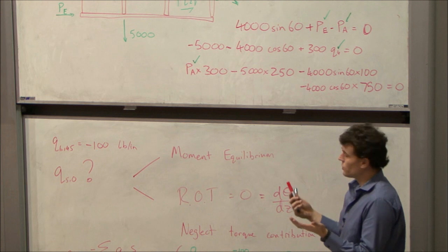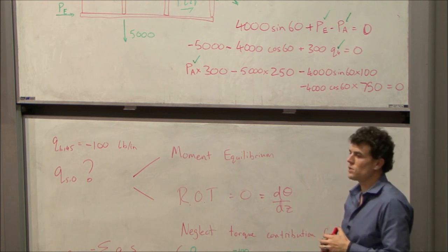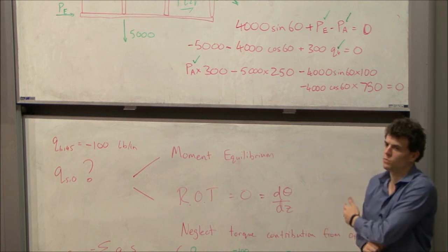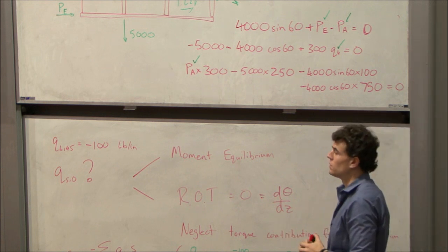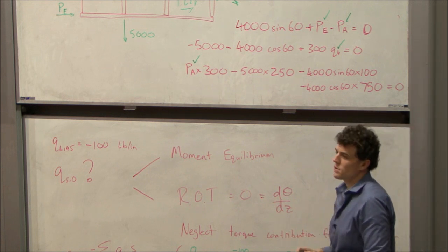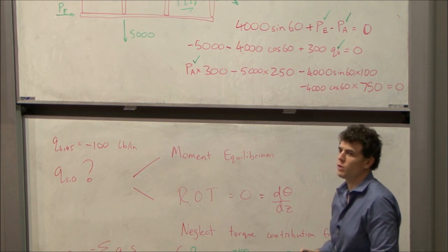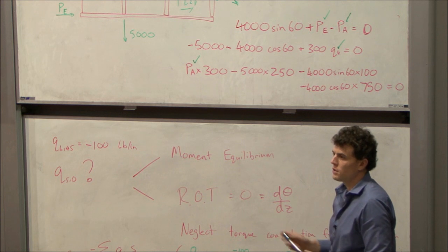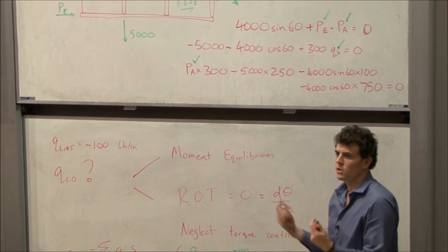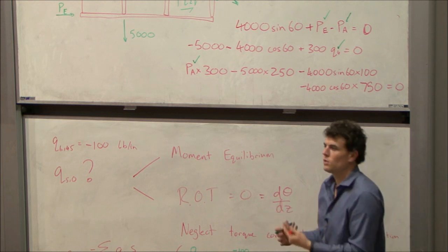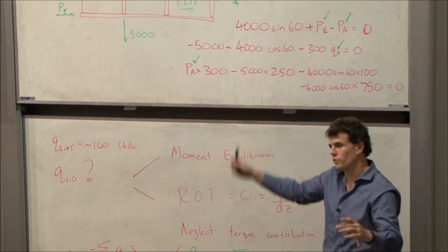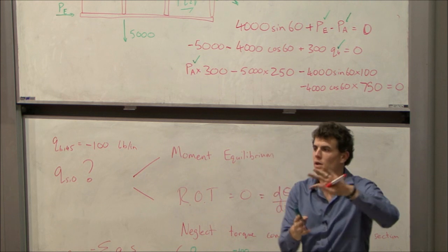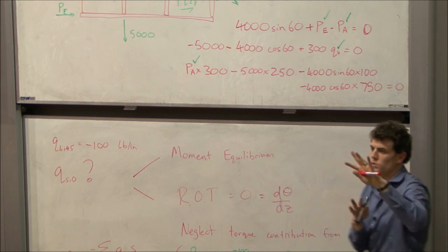So that's one way of doing this kind of problem. We can take slices anywhere we feel like and work out what the equilibrium on those slices is going to be. That's the equivalent of doing, say, a method of sections for a truss. You know your truss calculations: if you've got the whole truss in front of you and a force applied somewhere, you can just cut the truss and work out, based on where your cuts are, what the forces in the members are.